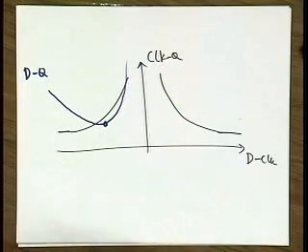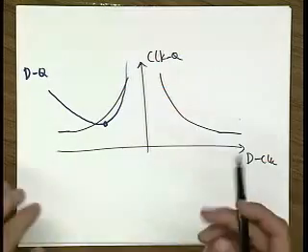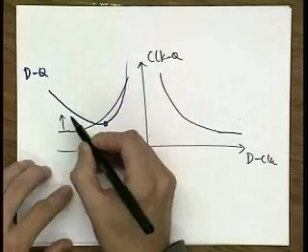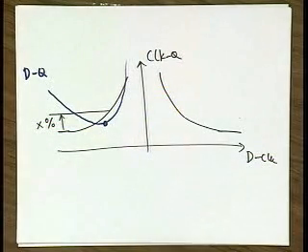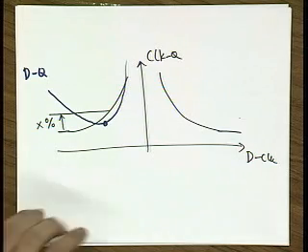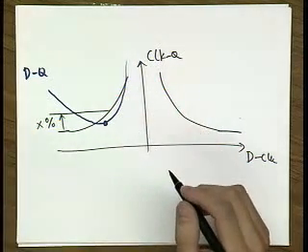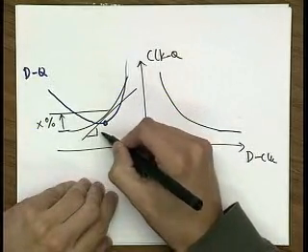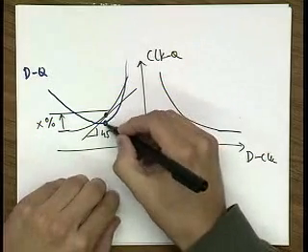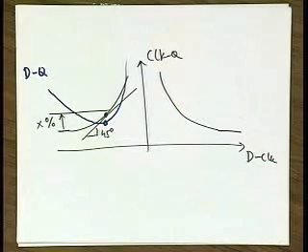There are a number of ways people do that. If you go from company to company, they have different definitions. Some people define it as, for example, some percentage increase from your clock to Q delay. They say, I can really reliably tolerate 5%, maybe 10% of increase in clock to Q delay, and that's my setup time. If I fail that, that's too bad. Some people say we are really keen on performance, so what we want to do is define this as a 45-degree line over here that basically minimizes this data to Q delay.